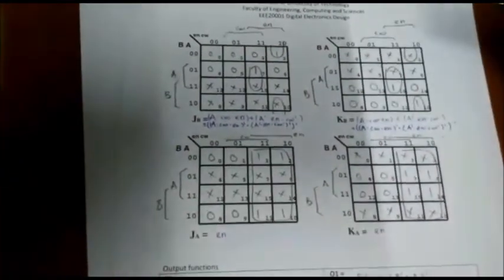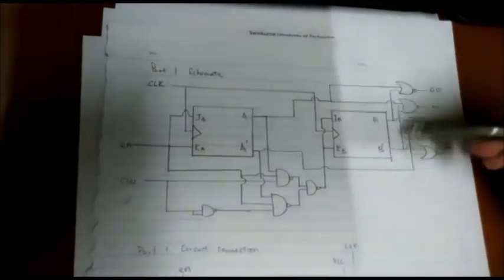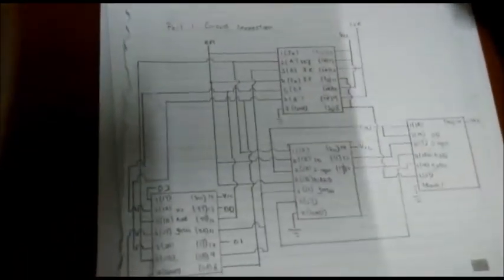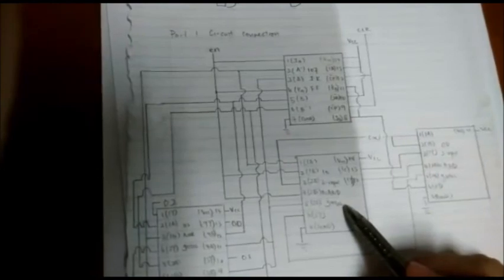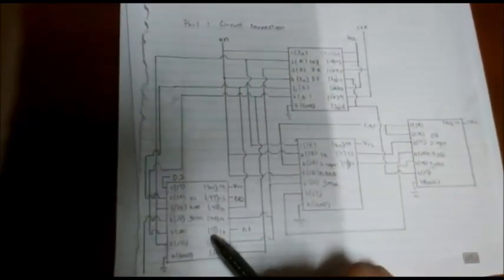With all the information here, we can complete the truth table. After we complete the truth table, we can get the equations of the J, K, JB and KB. So we can create the schematic and the circuit connection. This is the output. This will be our schematic diagram, and these are the circuit connections. For this one, we use one JK flip-flop, one 2-input NAND gate, one 3-input NAND gate, and one NOR gate. Now we move to the hardware part.